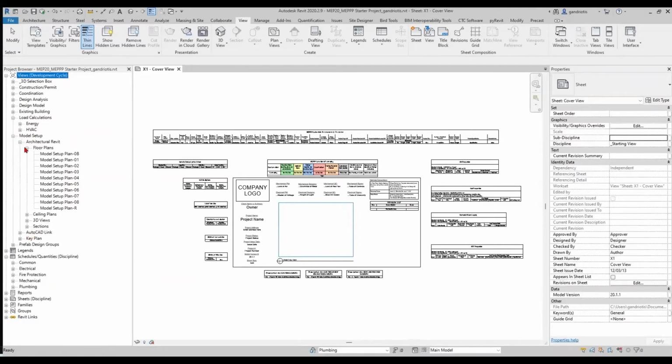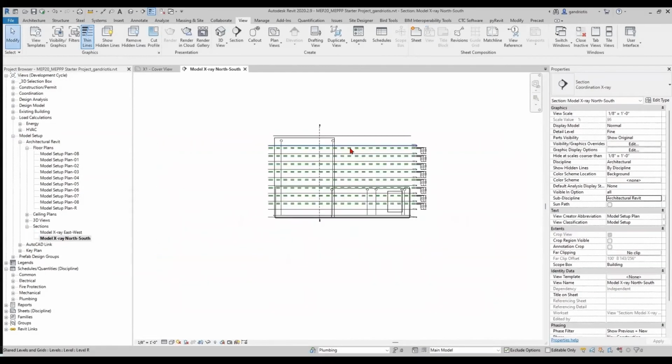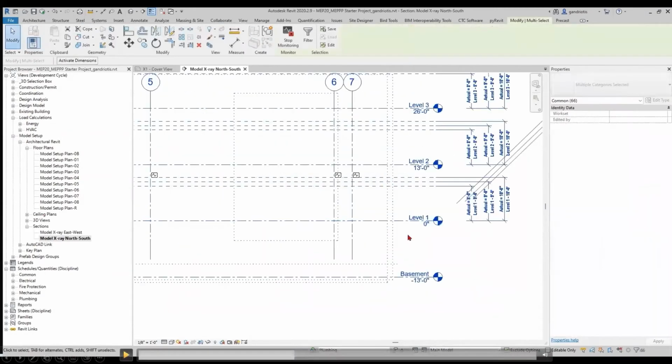We're going to go to a north-south section view. And let me pause it for 1 second. So what I'm doing here is I'm going to select all these levels, and then I'm going to stop copy monitoring them. Once I've stopped copy monitoring them, I'm going to filter this out and get just my levels selected rather than my levels and all my other nonsense. I think I even delete out the reference planes as well, because I don't need the ones on the other levels. And then I'll move my level roof down 20 feet so that it's somewhere in here. So I'll resume the video.